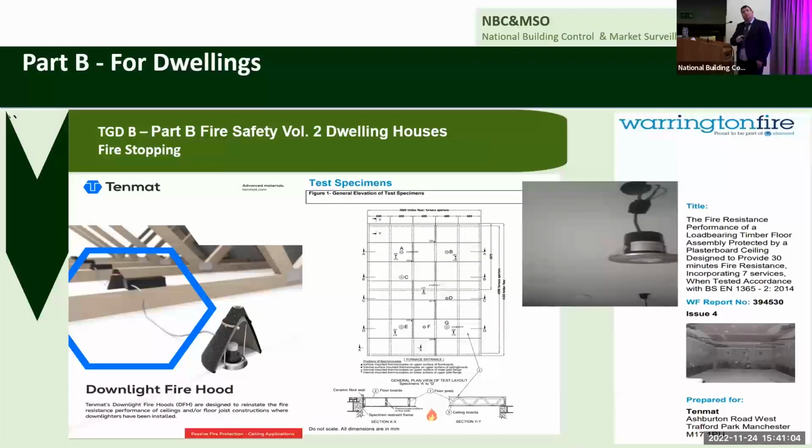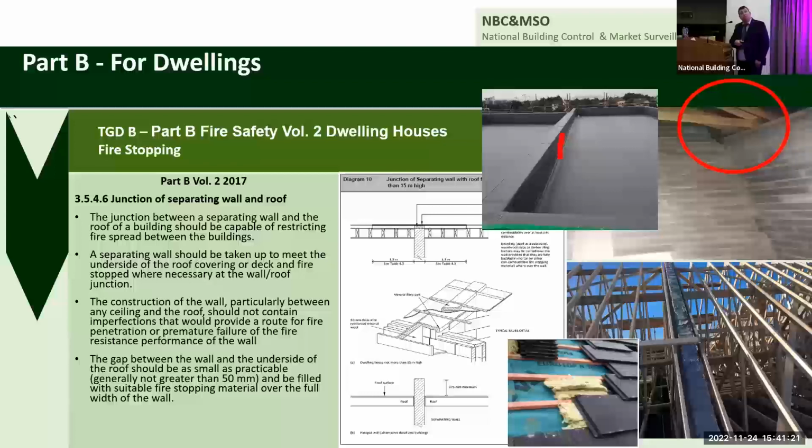In here, it's not fire stopped out to the external wall. And this is the flat roof. So you're making sure that between two houses here, that upstand is 375 mil minimum. Cavity barriers, you know, this is timber frame separating wall in the cavity here, not blocked off. You're hoping that that rock wool is continued on down there. It was a pillar, but it needed to be closed off there as well to make sure that if they'd run the head between the two, probably would have been sufficient.